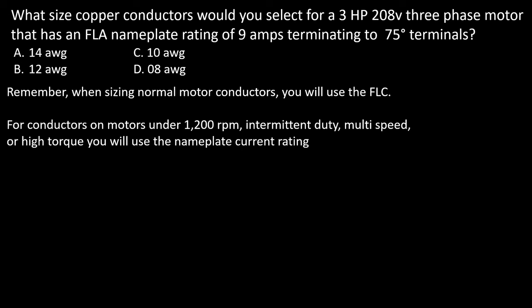This week, when you're dealing with normal motor conductors, we're going to use the FLC and not the FLA nameplate. When we're dealing with a certain special set of motors, we will actually use the FLA nameplate. I wish the code book wasn't like this. I wish they would just pick one or the other and stick with it, because it makes it very hard when you're testing. But I'm going to teach you this week and reteach you, because we've learned this in the past. This is the Master Series. This is all about you already knowing this much, but I do want to recap so it's fresh on your mind. All right, so let's go ahead and jump in.